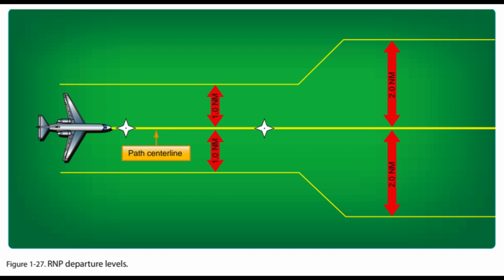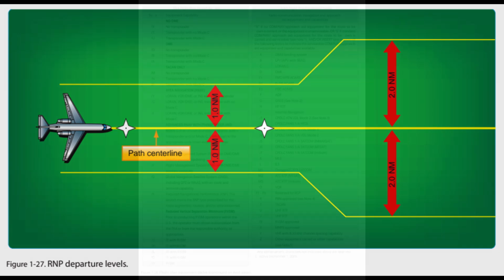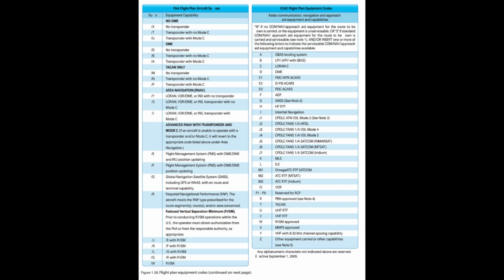This is limited only to systems that allow along-track waypoint construction. Pilots of aircraft utilizing DME/DME for primary navigation updating should ensure any required DME stations are in service as determined by NOTAM, ATIS, or ATC advisory. DME/DME navigation system updating may require specific DME facilities to meet performance standards.